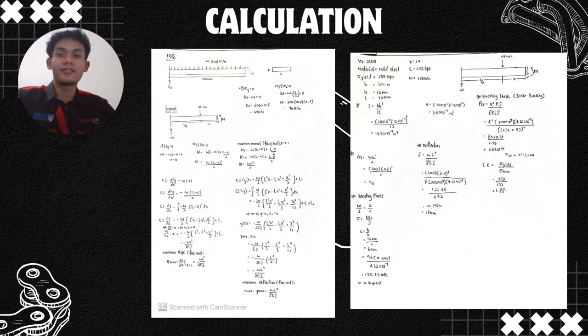So next, this is the important part of this project, which is calculation. The beam has a length of 800 millimeters and is fixed at one end with a load of 300 Newton per meter acting along the beam. From the free body diagram, the total load on the beam is 240 Newton and the reaction force at the fixed end is also 240 Newton. The maximum bending moment occurs at the fixed end and is calculated as 96 Newton meter.